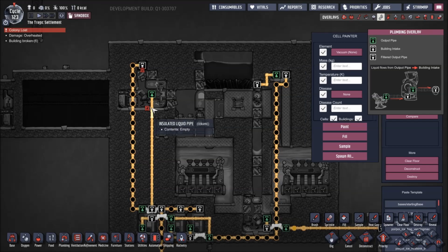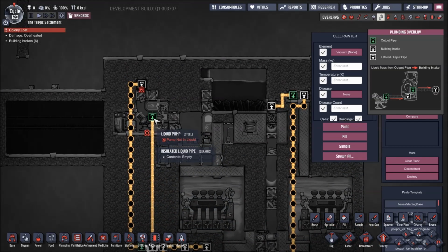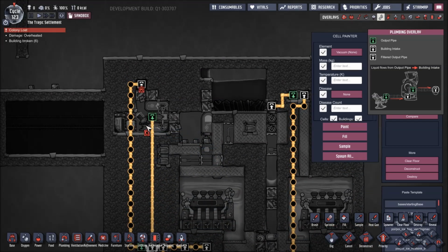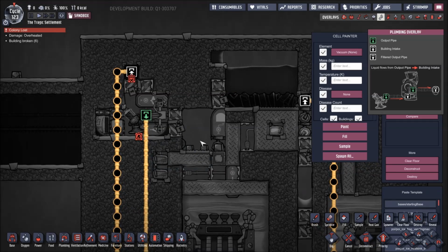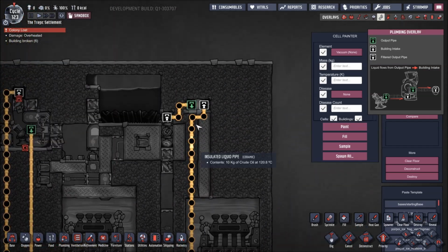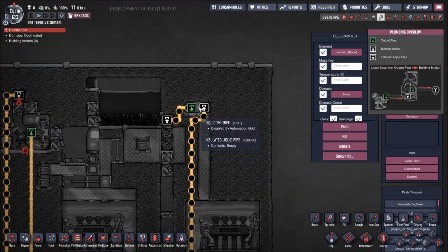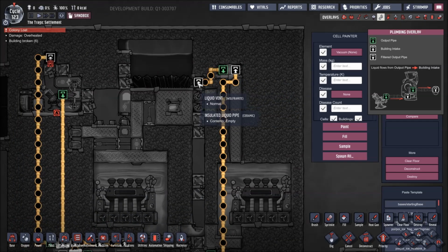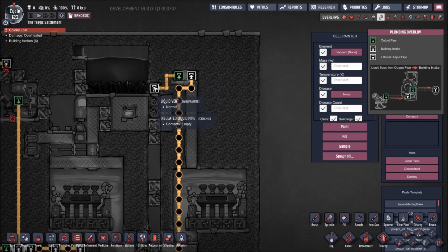And that's important because if we ever had oil back up all the way to this room and the pump not be able to pump, when this door opened, we would spill oil in here, and then it would heat up and we get sour gas everywhere, and it'd be just horrible. So here we have the output of the oil just going up to our shut off here, where then it goes into the valve or the vent.